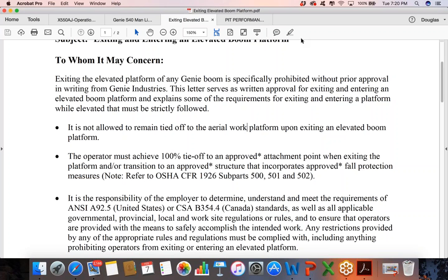So things that we want to make sure of are the following items that we have to consider before we start any type of steel erection, right? So, loose clothing and accessories. We want to make sure that we don't wear loose clothing, right? We don't wear torn clothing, right? Or rings or jewelry when we're doing any type of steel erection. Okay, clothing and accessories. What happens if they don't fit tightly? Hey, they could get caught in some type of moving machinery, right?